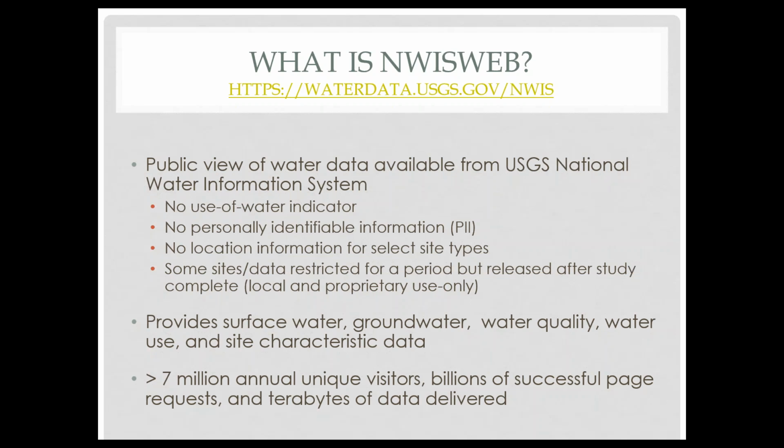So we will often put down a borehole camera and look at the integrity of that well. Or we may pump the well and say, it looks like it's got a good signature, it's pumping, it's not clogged. So you want to consider, again, the location of the well, the construction of the well, the site characteristics. Is the site accessible? Can I get in and out on a regular basis? Can I safely put instruments down that well?